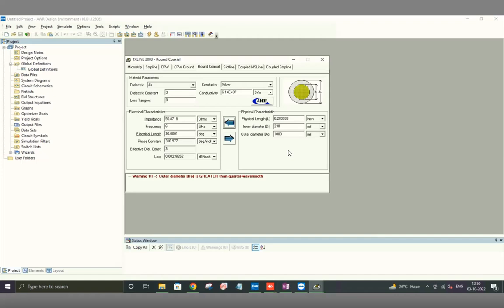So that's coax. To summarize, one of the important points here is the field everywhere is going through the same dielectric. And that's why this effective dielectric constant is the same. Just to add another point, it basically affects your capacitance per unit length. If your field is not present only in the dielectric and also in air, energy will then be distributed differently.